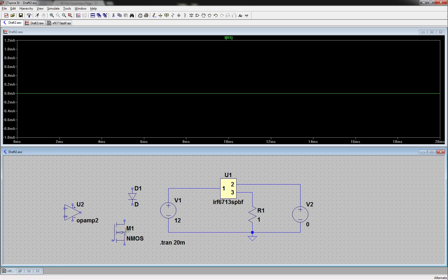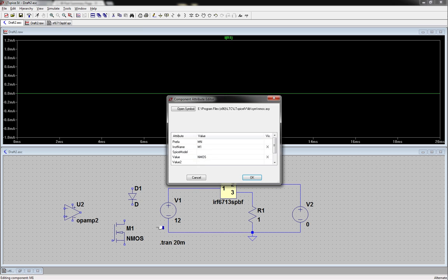So I don't like using this symbol and doing Control and then right click and then changing it, because with power FETs they have that diode, and I like to be visually reminded that the diode's there, just so I don't run into trouble later. But you guys do what you want. There is no reason for it. That's just my own personal thing that keeps me from getting tripped up.